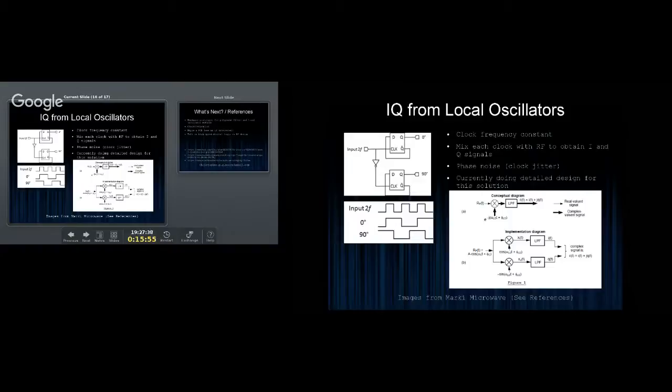So this is your clock, and these are the outputs of your D flip-flops, which are non-inverted. So there's a quadrature signal. Now they're square waves. This is really, really interesting when it comes to mixers, but I have a feeling this is a talk for another day. And I'd like to be able to do that when I've actually built it. So it's probably going to be a lot more fun.